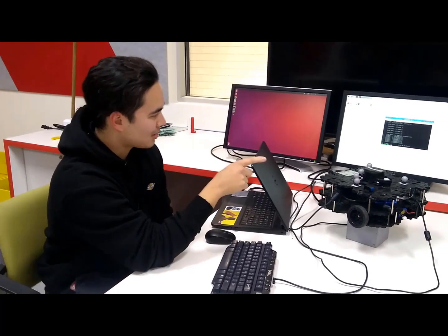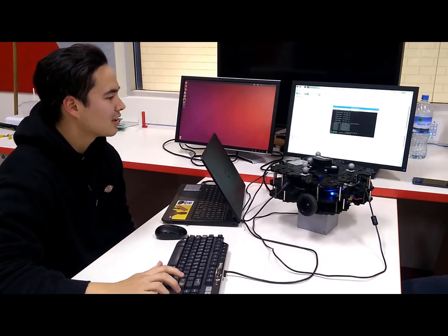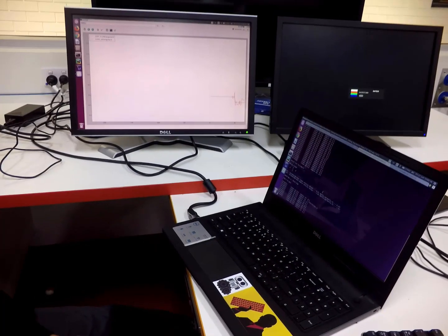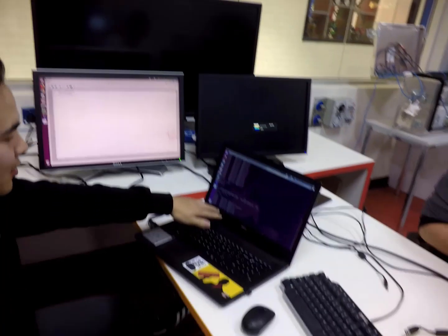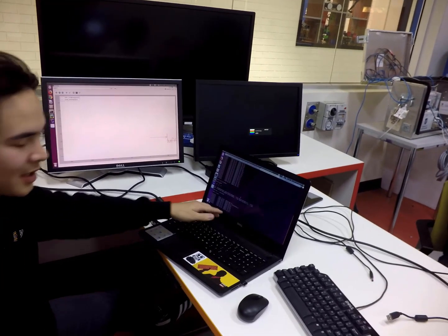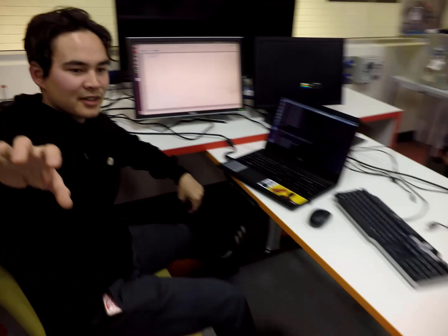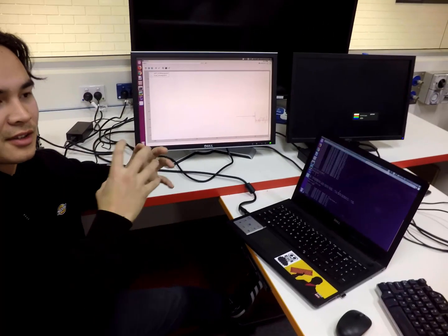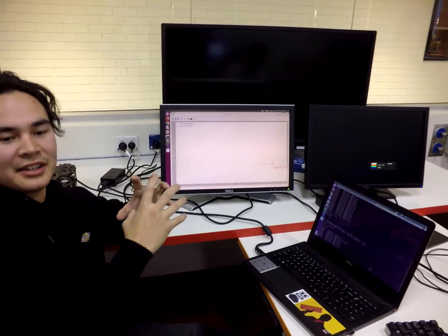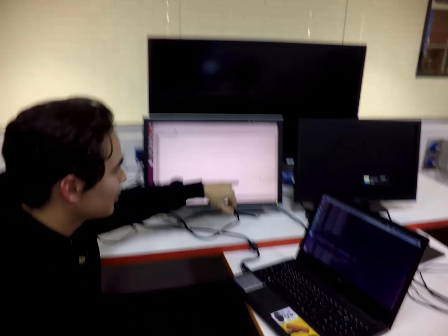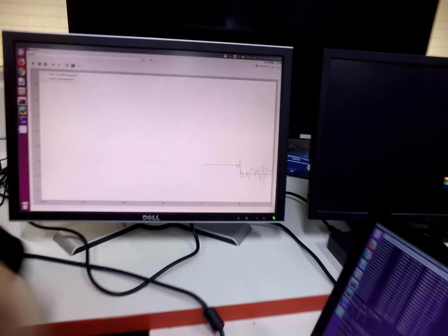I use Indo, and for my AMS extended task I did Optical-Flow. On this monitor I've got a demonstration of what that looks like. The robot is rotating at a constant negative 0.3 radians per second, and my Optical-Flow algorithm, using the features that it can see, calculates the flow, the distance between how those points have moved, on an interframe basis, and then plots that, and it approximates around.